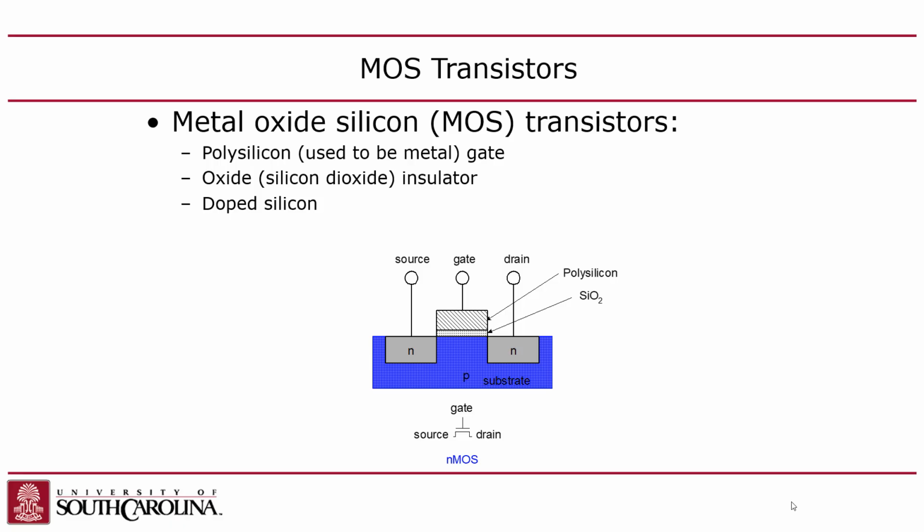Well, I shouldn't say back to N-type, but it'll transition it, right? So I started out with boron atoms in here, and then I hit it with the arsenic, and I can create these two little islands of N-type inside of a P-type lake or substrate, right?